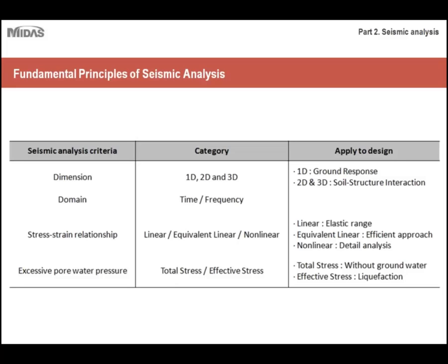So depending on the type of analysis you run, for example, if you were to run an analysis for how soil responds to seismic loading when it's drained versus undrained, the results would be very different. So for example, when soil is undrained and seismic loading is applied to it, that soil will actually behave as a liquid in a phenomenon called liquefaction. We won't be going into much detail about liquefaction, because that's a deeper concept that would require its own presentation.